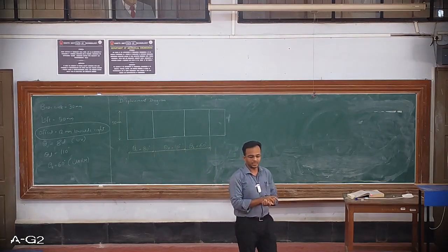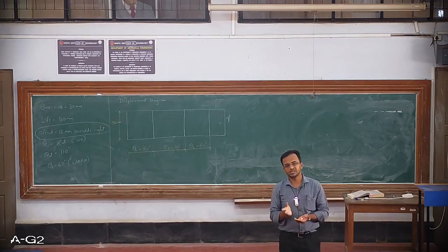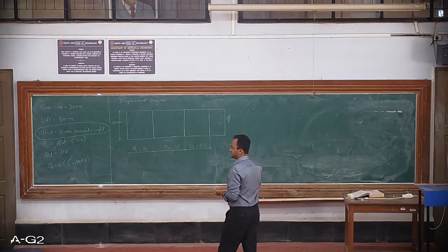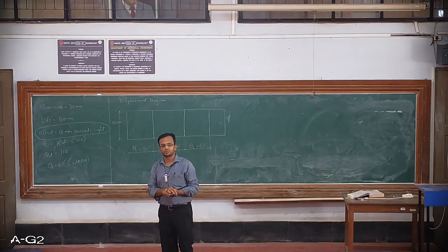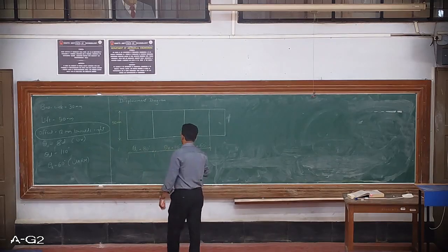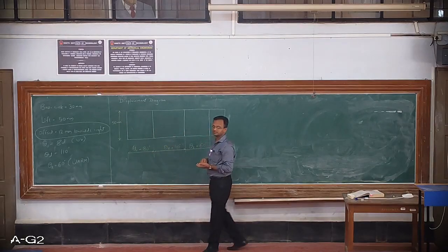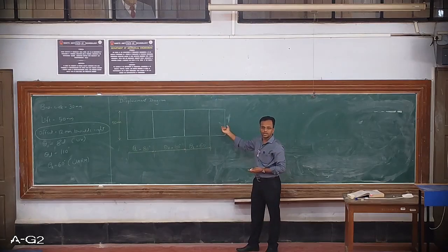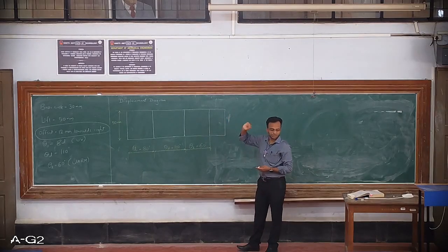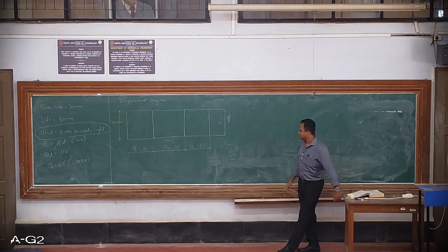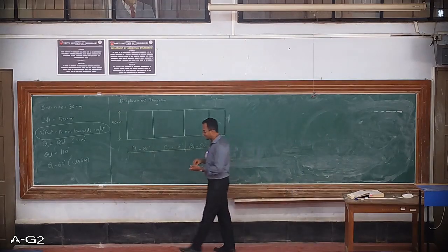So if you are taking 6 divisions, just ensure that 6 divisions are there in rise stroke as well as 6 divisions are there in the return stroke. So you can choose even 8 divisions, but for that your scaling should be better. You cannot draw a very small diagram and make 8 divisions in that, so the drawing will become too shabby and it again leads to confusion. So I suggest you to go for 6 divisions.